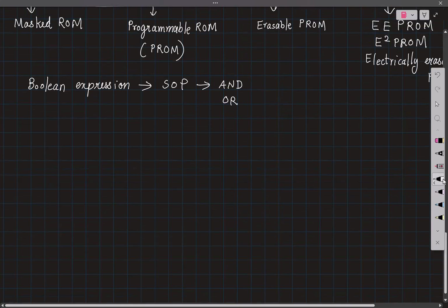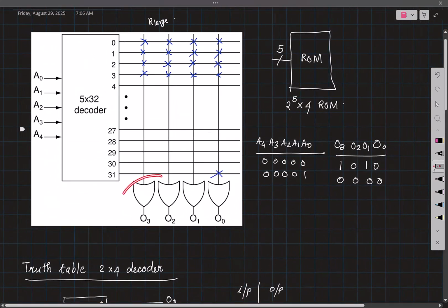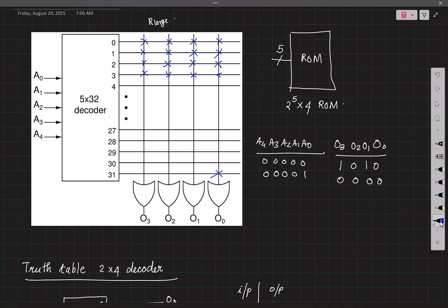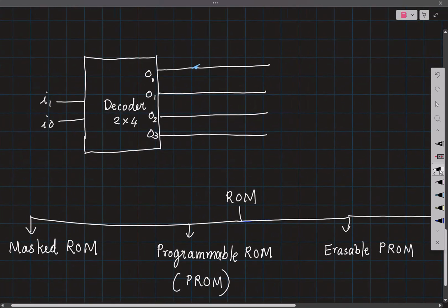Now already we have seen that our read-only memory has the functionality of the OR gate, right? So the only thing I need to check now is if this decoder is somehow giving me an AND gate functionality, right? So can you quickly tell me, what does the function at this point look like? When does that go high? I can take a simpler decoder. Let's say I look at this 2:4 decoder. When does this pin go high? When I1 and I0 are 0, right?